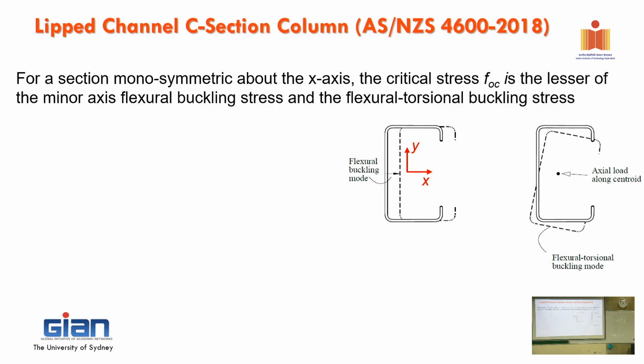So imagine this is a channel section. Okay, this is the major axis, very hard to bend this way. But this is the minor axis. So if the column is very long, when you push, boom. Sorry. But that is really a demonstration of how the column reaches buckling load. It really buckles, exceeds the yield. Exactly. So that really shows you this is buckling about the y-axis because it's so weak.